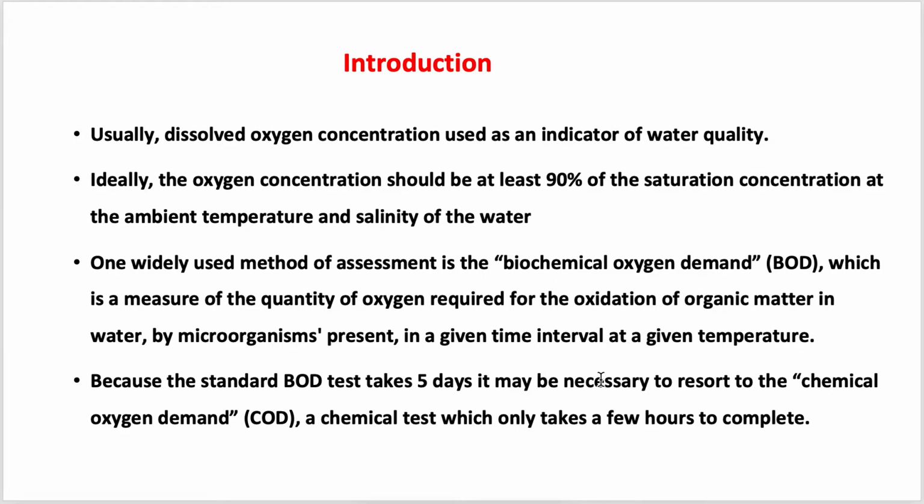So that's why an alternative, called COD, chemical oxygen demand, is measured. The test by which COD is measured takes only a few hours. So basically people measure both COD and BOD, but initially they measure COD because it takes less time. Then they also measure the BOD. Measuring COD and BOD is especially important for effluent treatment.